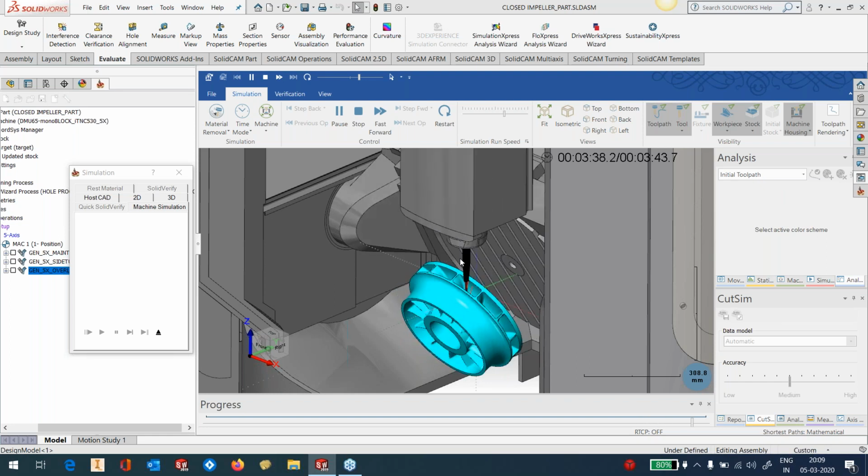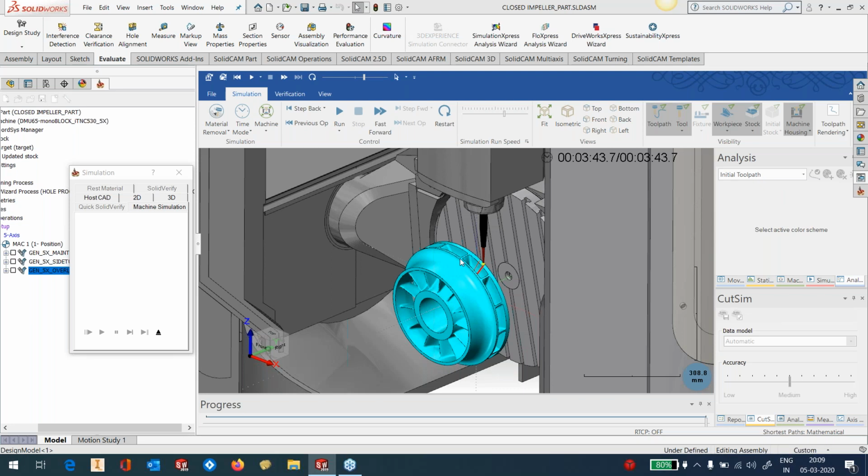Now, this full tilting is happening because it was going very close into that radius area. The radius is completely, it just cannot be seen even from the naked eye from the top. So it literally needs to tilt it to about 115 degrees. The table has to be tilted to about 115 degrees to approach that radius. So that's the kind of tilting that it was doing.